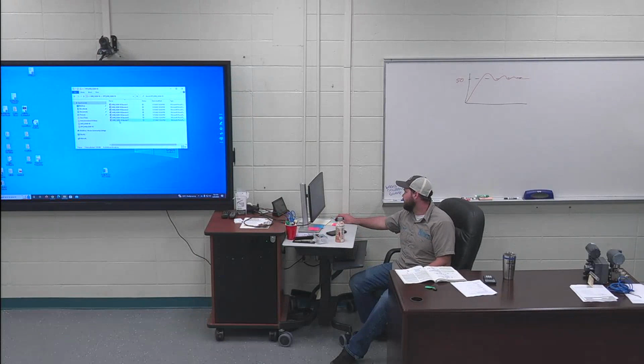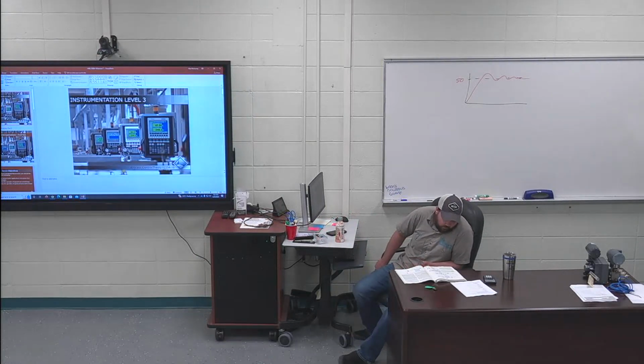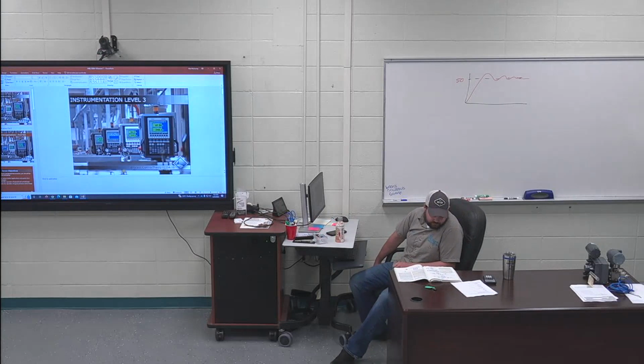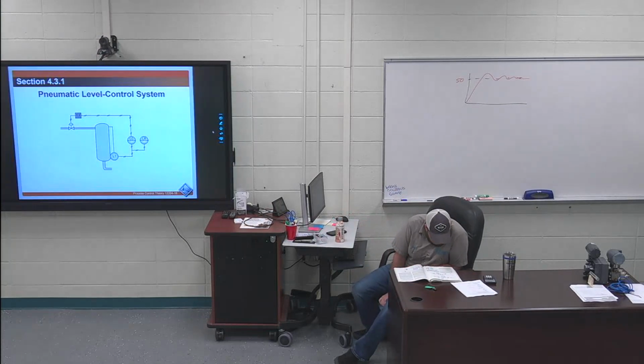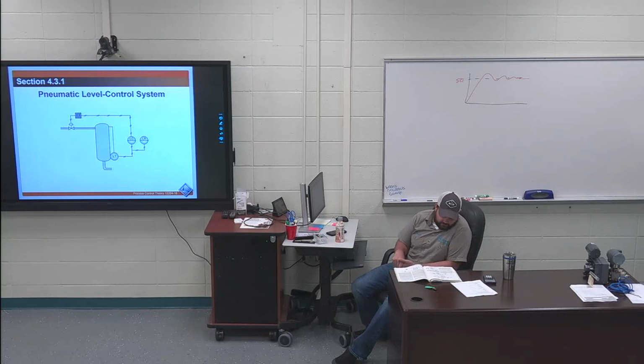430, which probably is the last section. 430, typical level control loops. Pneumatic level control loop. 431. The third and fourth sentences on 431 are highlighted. A flange mounted diaphragm type differential pressure transmitter, LT, measures the level of slurry, the pneumatic output of the transmitter sent to the level controller in a level recorder.